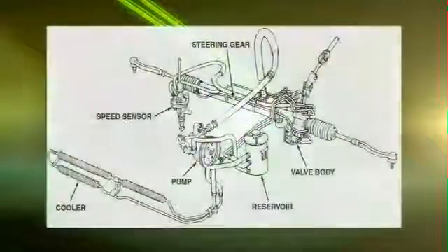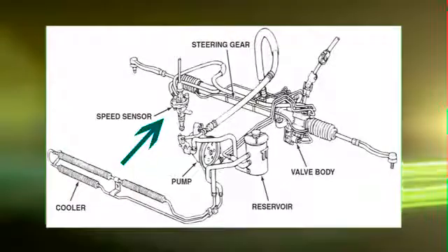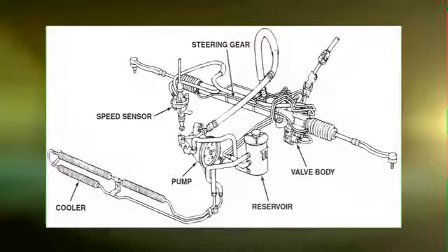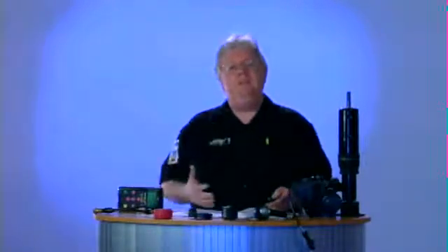All right, let's talk about power steering now. Power steering has been around for many years, and we're starting to do some things with it, like replace it with electric power steering. But this is hydraulic power steering you're seeing in the figure, with a speed sensor in this particular picture. We're going to talk about that kind of system where we vary the effort for power steering. We can make it a little bit tougher to turn the wheel or a little easier to turn the wheel based on vehicle speed and maybe even steering shaft or steering angle inputs as well.